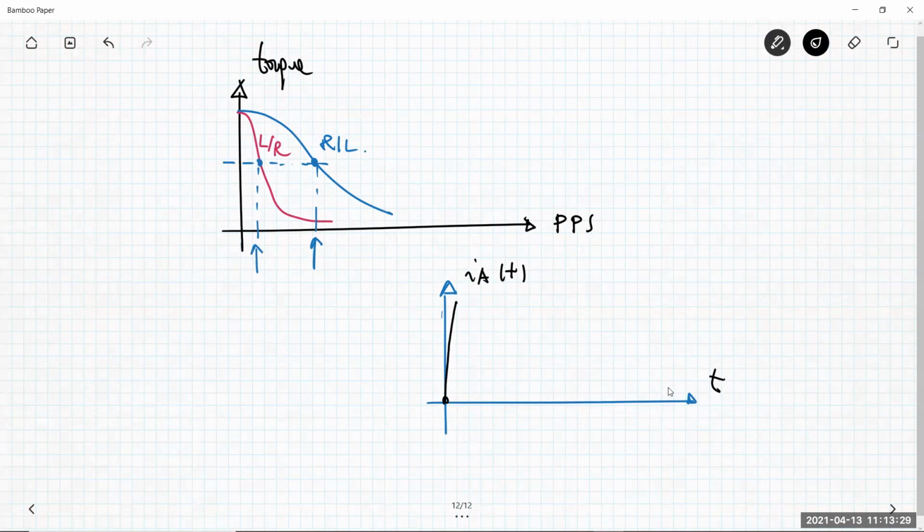Of course, if I use this voltage here, my current will be very huge, because this is V over RA. RA is fixed by my motor, and V is the large voltage I am employing. For example, this voltage is several times larger than the maximum voltage that the manufacturer established in the datasheet. So there's no way.